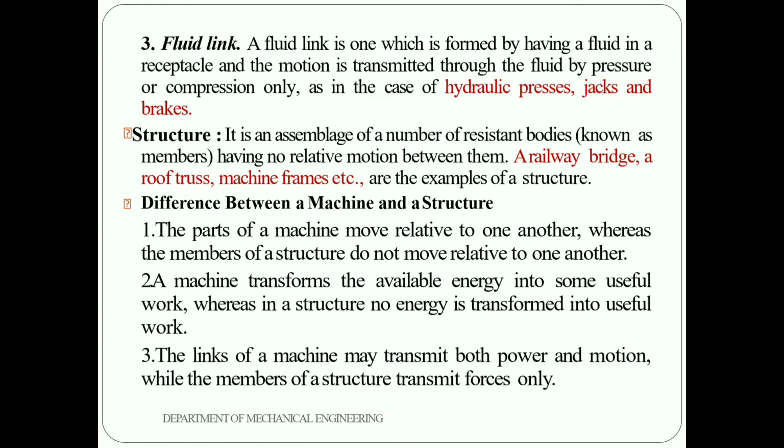The parts of a machine move relative to one another, whereas the members of a structure do not move relative to one another. A machine transforms the available energy into some useful work, whereas in a structure no energy is transformed into useful work. The links of a mechanism may transmit both power and motion, while the members of a structure transmit forces only.